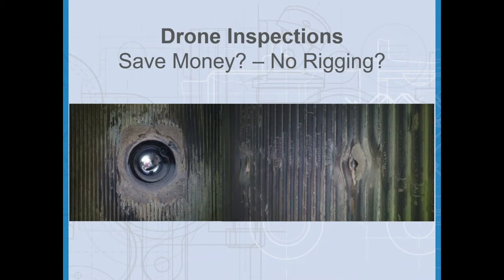Drones are becoming more popular for inspections, and they're good in certain applications. However, if you do employ drones, keep in mind that it's visual only, and it's only from one frame of reference. If you've used borescopes for inspections before, your frame of reference is sort of thrown off, and small imperfections can look very large with a borescope. It's similar to that with drones.